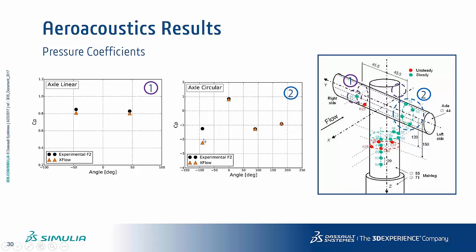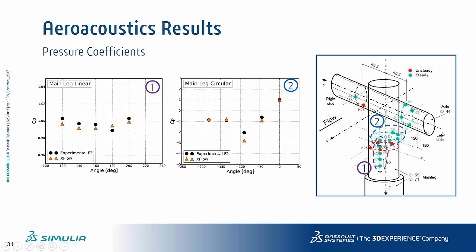Maybe the point here at minus 90 degrees is slightly underestimated here. That means maybe prediction of separation was too strong here, but on the other side it was correct, and then also on the separated area next to here. Now we've got also good match about 0.8 of pressure coefficients at zone 1 as well, which was good and close to the experimental data.